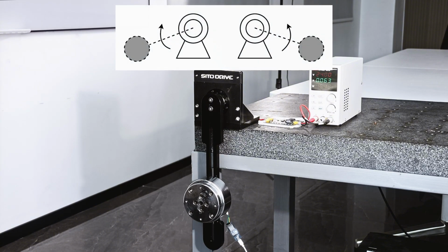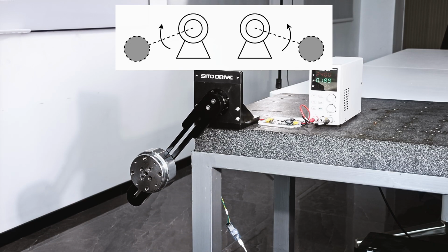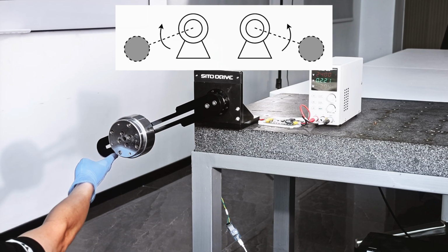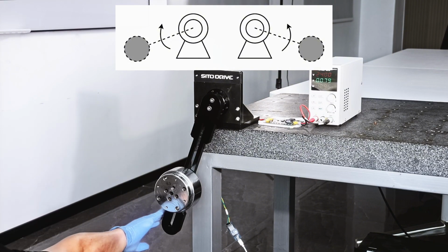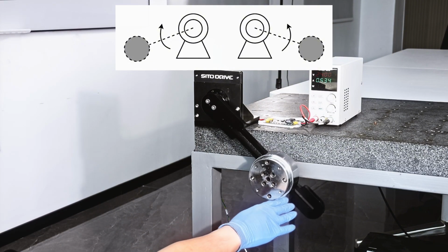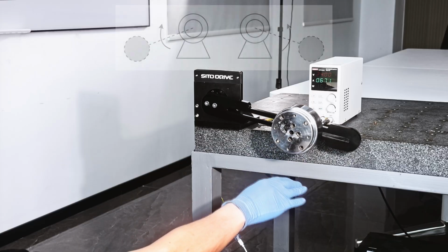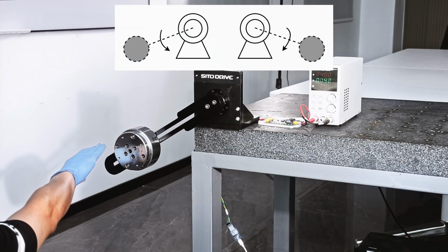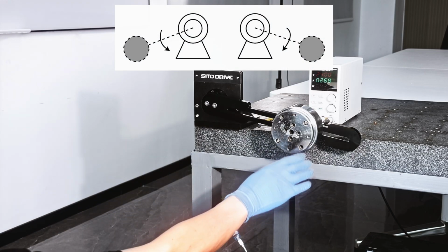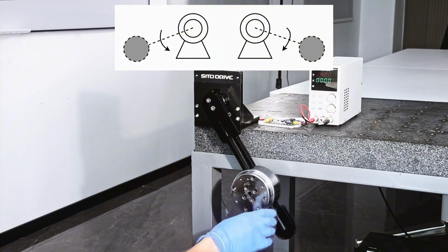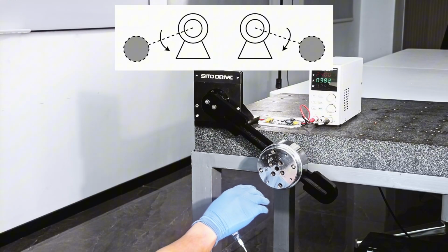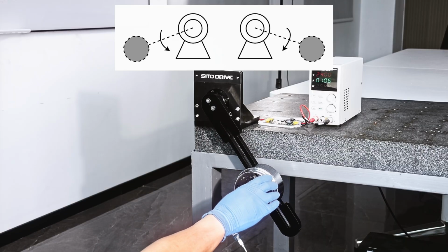For example, if the actuator decelerates significantly when the rotation direction is the same as the torque direction, increase the frict_param_assist or frict_param_assist_neg parameter, otherwise decrease it. If the rotation direction is opposite to the torque direction, adjust the frict_param_resistance or frict_param_resistance_neg parameter in a similar way.